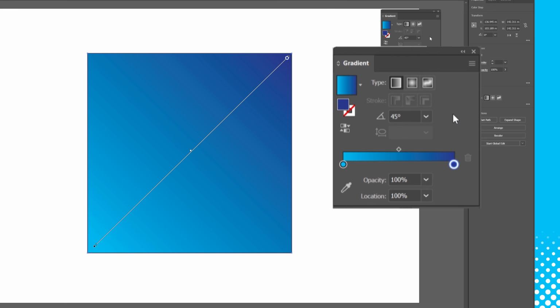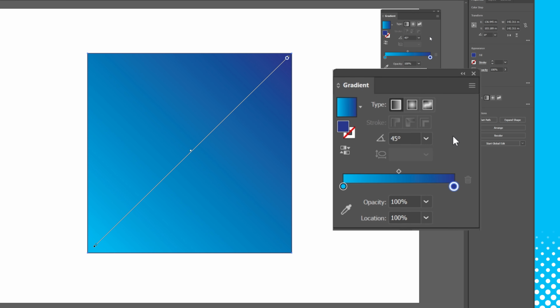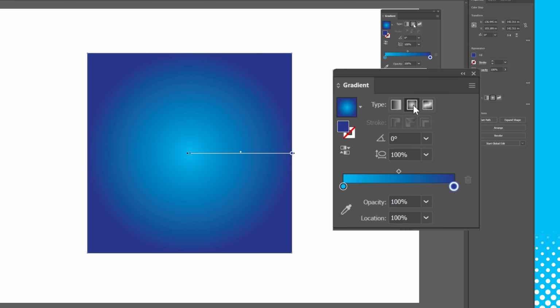Anyway, now that we've changed the gradient colors, we can go about stylizing them. Going back to the type of gradient, we have linear and radial. Linear is just a simple gradient from one end to the other, but by contrast, radial peaks at a certain point of the gradient. By default, the center will be in the middle, but if we grab the little handle at the center and move it, we can adjust the central point of the gradient. Radial is circle-based, so we can also change the maximum radius of our secondary color, which is this one.